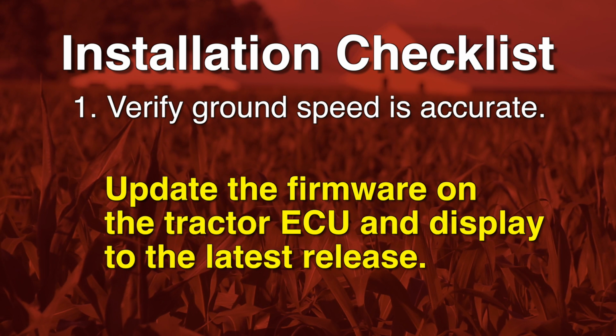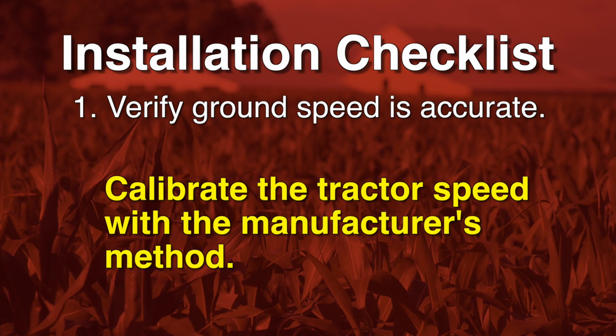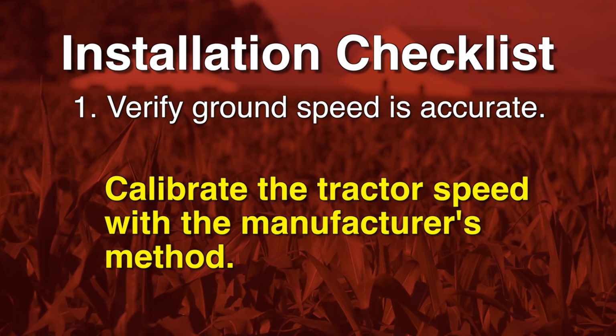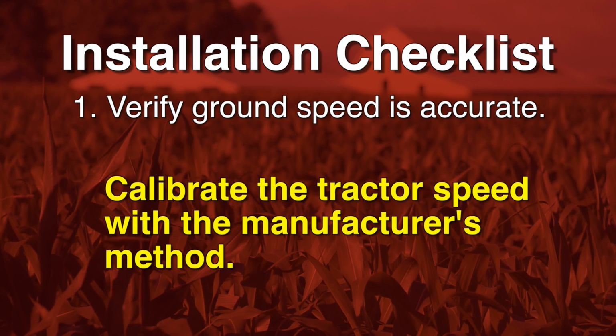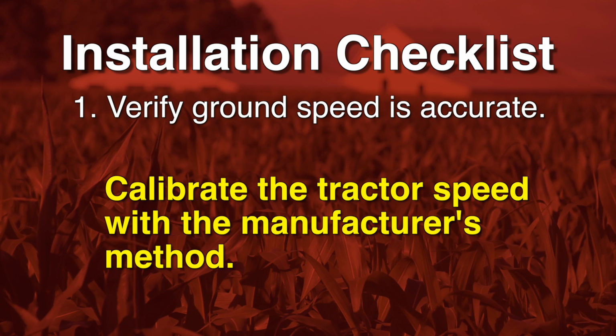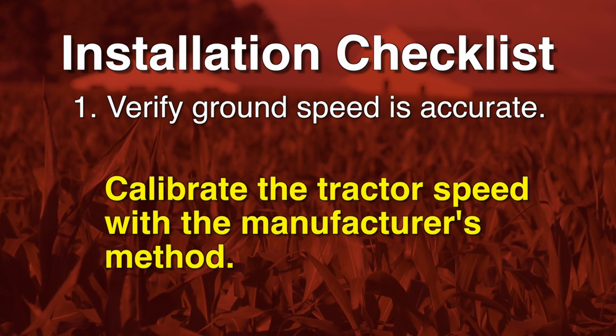If the tractor speed is not correctly calibrated, you may see a discrepancy between the A-post speedometer speed and the ISOBUS display speed. Because the ISOBUS is getting its speed from a GPS source, it's most often accurate. The solution is to use the manufacturer's method to calibrate your vehicle's speed.